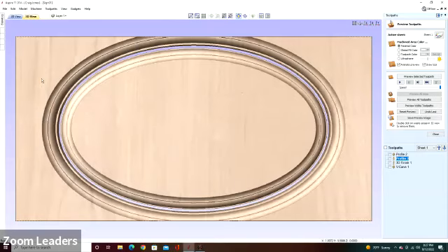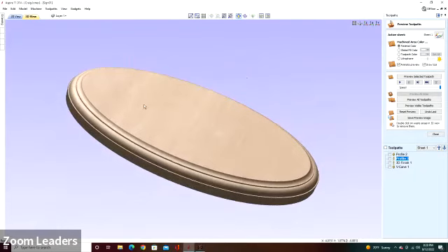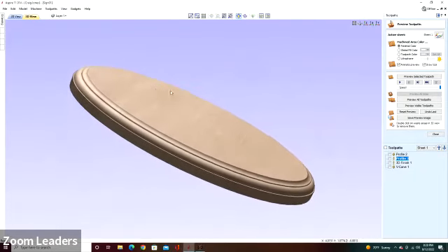Now, earlier I mentioned that you can start from the top of the board or the bottom of the board. If you're doing a lot of through cutting, you typically want to start at the bottom of the board so your bit doesn't go below that and cut into your spoil board. I've cut into the spoil board hundreds of times. And another thing you can do is say, all right, now I've got my shape. I'm going to eliminate the excess material and start looking at it. And that's kind of what I'm trying to accomplish.